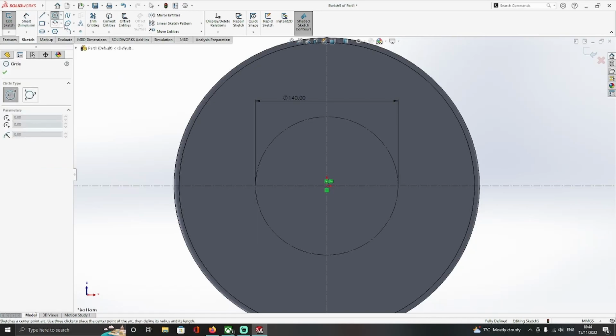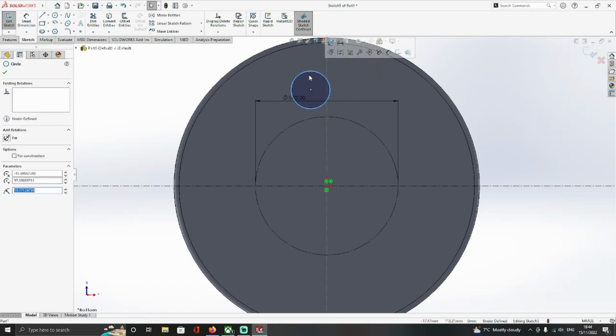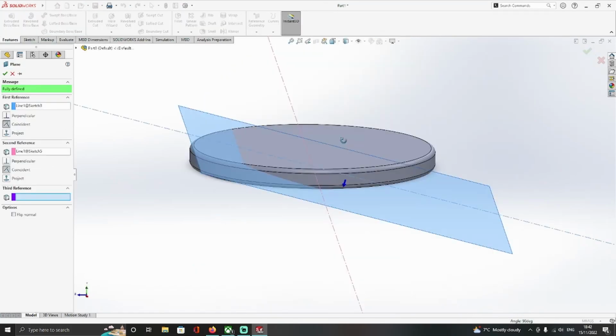Now, a bit of stupidity on my part. I decided for whatever reason to create the circle to extrude the leg from on the same sketch as the circle the leg is aligned with. That was stupid. I should have made that on the same plane that we had just made previously, which was angled at 15 degrees.